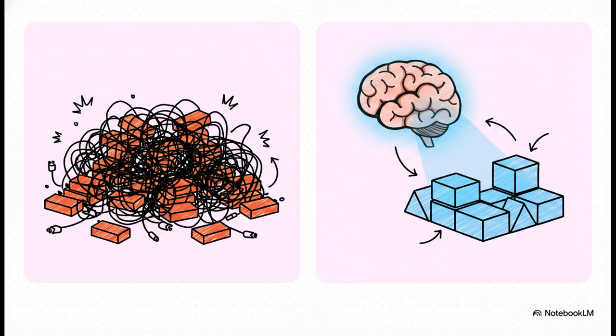Instead of mapping out physical gates, you just describe the function naturally. You simply type assign S equals X bitwise XOR Y bitwise XOR Cin. It represents the exact same physical circuit under the hood, but it's vastly easier to read, write, and debug.